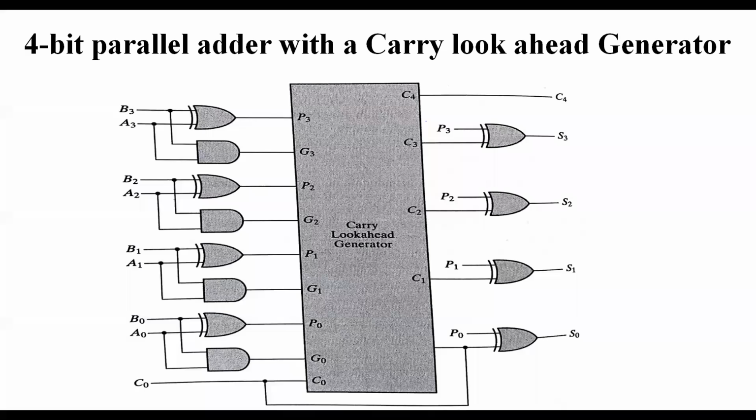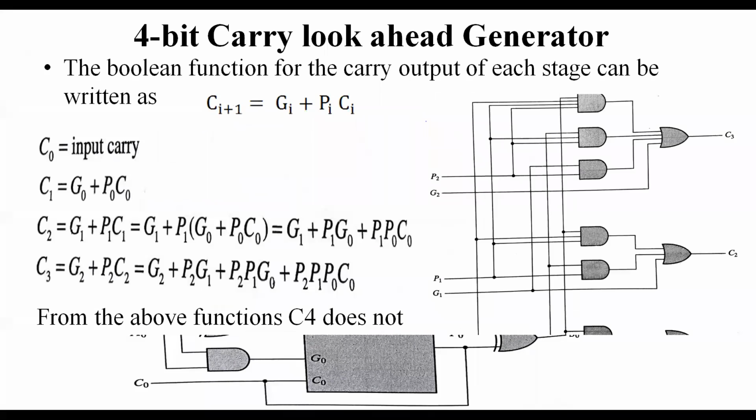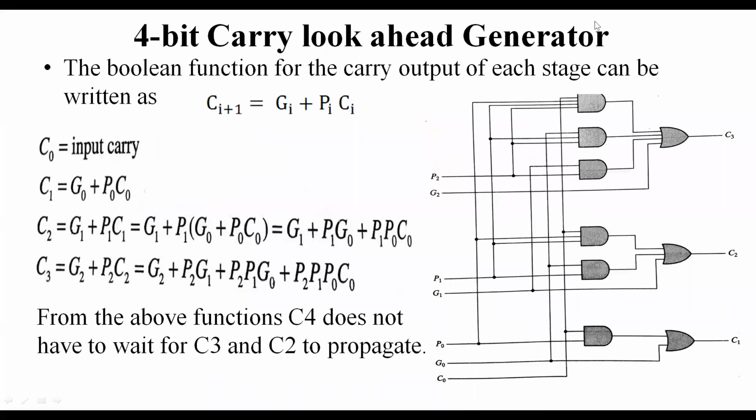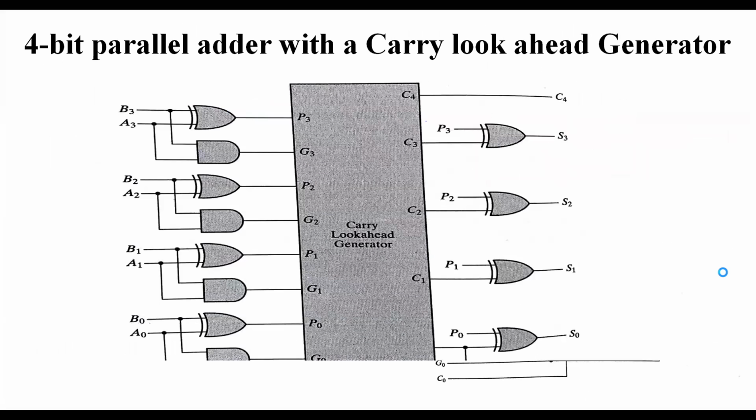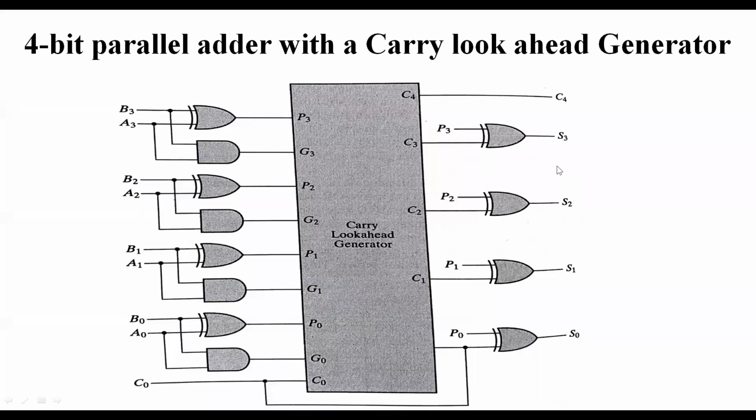When compared with the 4-bit binary adder, the look ahead carry adder will be faster with respect to the propagation delay of the carries. Carry propagation delay is directly reduced. This carry look ahead adder circuit directly generates the carries; the intermediate carries are generated directly. These carries are connected to the final sums. I am connecting them to the sums, so the sums and carries have a chance to respond quickly without delay.